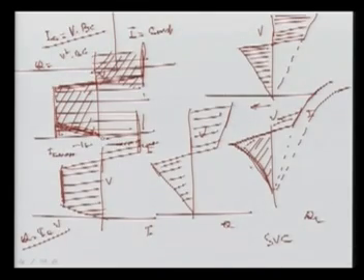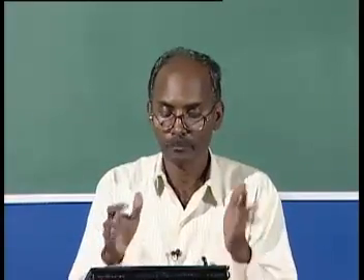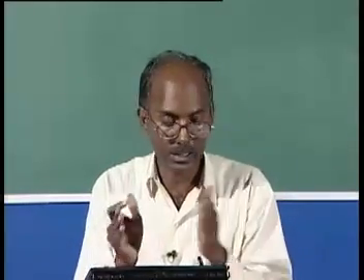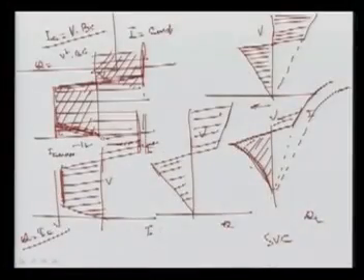So the STATCOM is better in terms of dynamic range. It has a wide dynamic range, a better operating range, and also more overload capability, meaning we can go for more current on both sides. Here, only on this side can we go for more current, and normally we require it in this capacitive zone. So this is basically the difference between the SVC and the STATCOM.